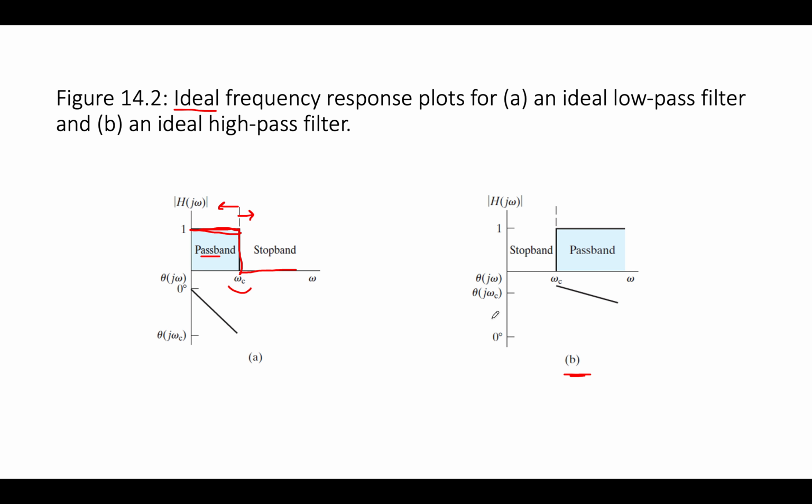DC drift is a common thing if you have a ground and it's not like a hard earth ground. Sometimes grounds can do what we call float. They can move a little, so you get a little bit of very low frequency DC drift in your signal. That's not that uncommon, and so the passband can be used to stop DC.